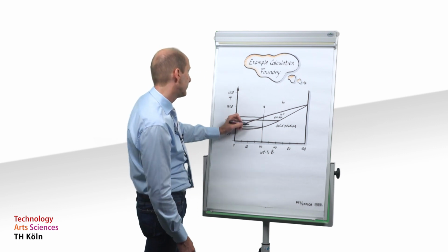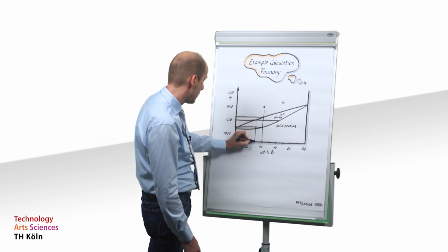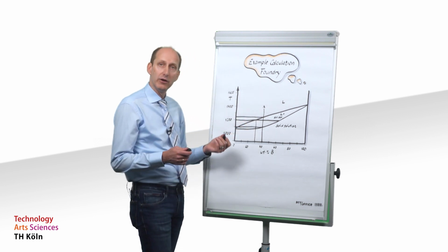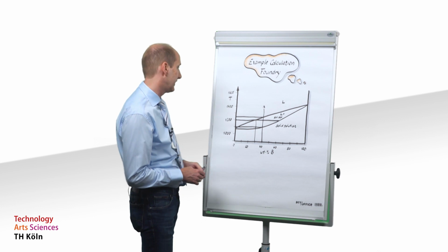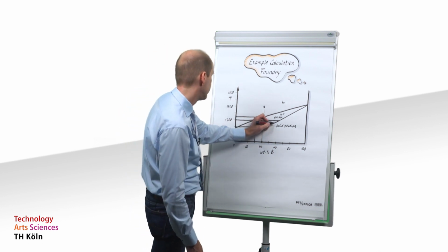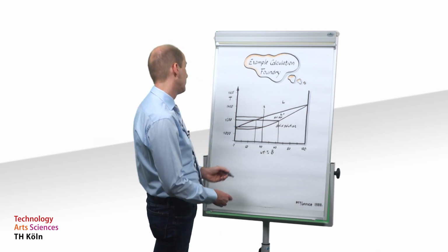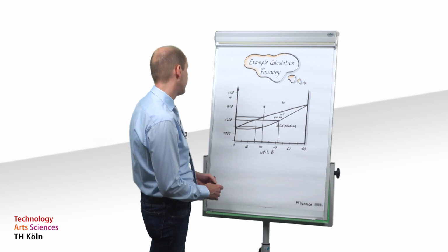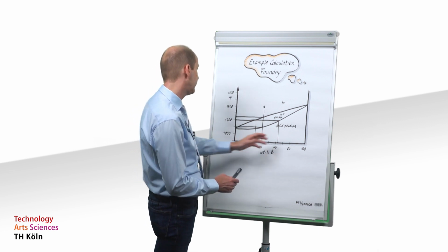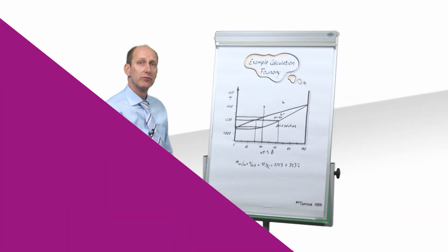with the liquidus show a composition of the melt of 30% B and of course 70% A, whereas the intersection with the solidus shows a composition of the solid solution of 26% B and 74% A.